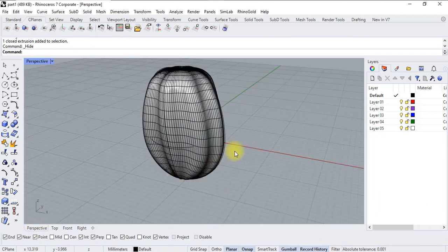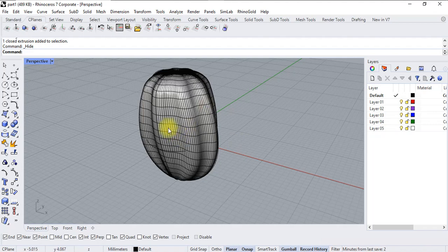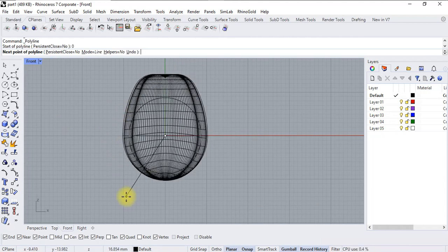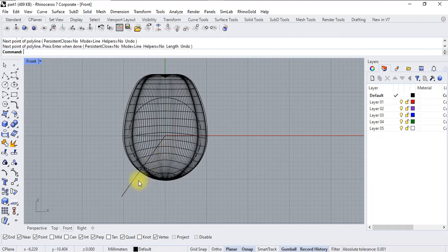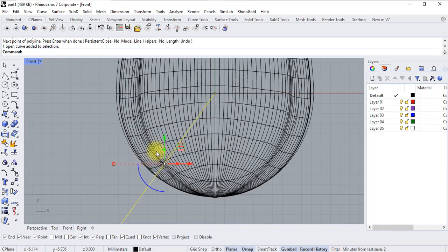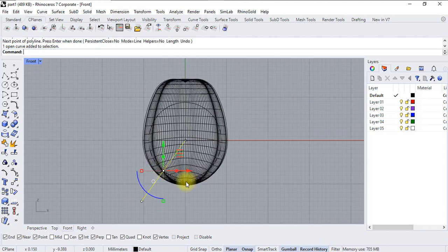Okay, so in part 1 we have created up to this level. Now go to front view, just create a line, start from the 0 and click the proper angle and use the symmetric way. Okay, so this intersection is very important, up to where you want to cut your bottom shank portion to stretch your bottom shank.